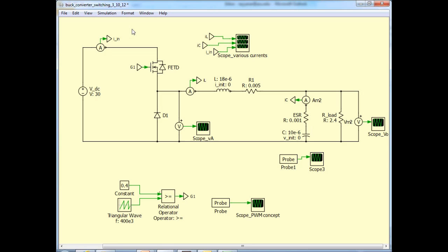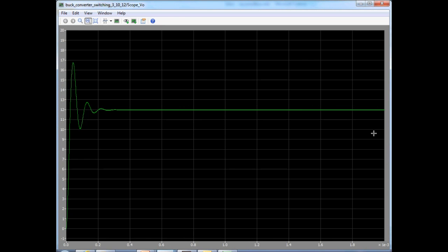So even with the much smaller time steps, we can see that the simulation did not take any time at all. It's already completed. With this changed output capacitor, the thing that is really changing is the output voltage and its ripple wave shape as well as the magnitude. So let's look at the output voltage in this scope. The first thing you can immediately notice is the effect of the significantly lower value of capacitance.